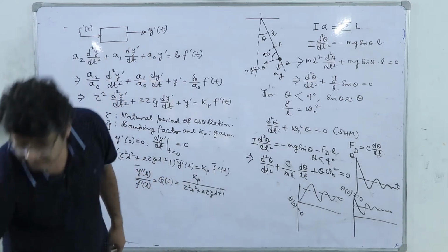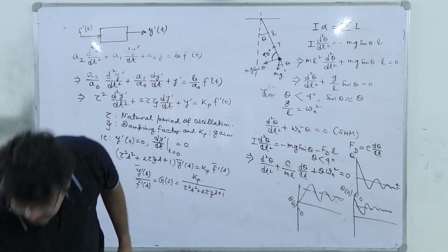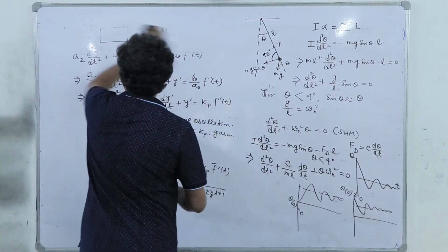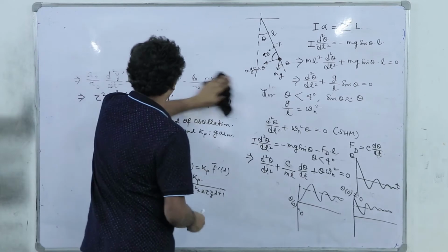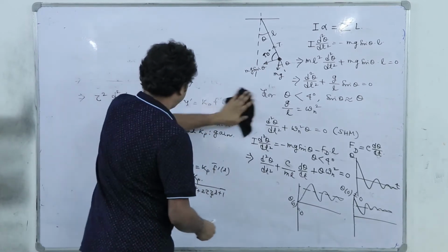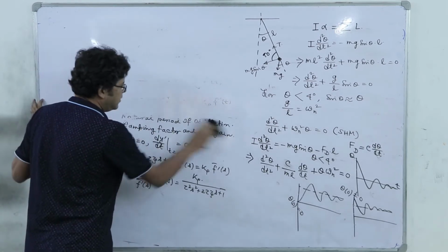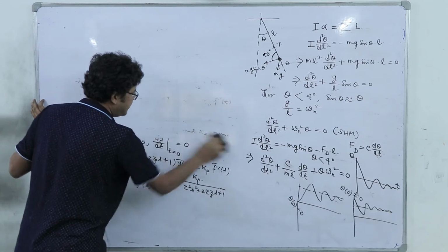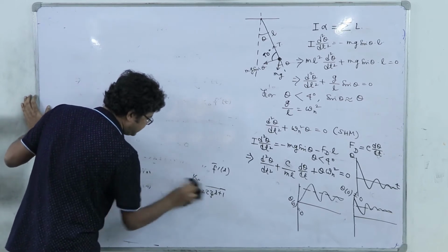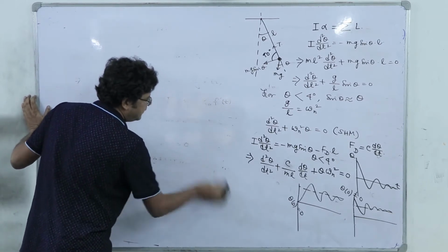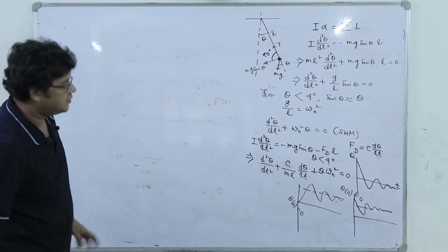So under this situation, what will happen? We have to include the moment produced by this external force, that is F. That force is an external force and it is acting constantly on the dead weight of this pendulum, and the pendulum dead weight attains some fixed theta value not equal to 0 after some initial oscillation.